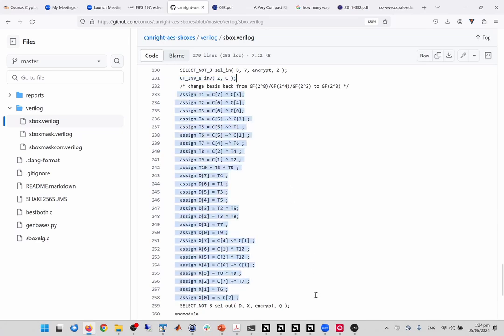And then based on which polynomials you select for the conversion in this tower field, they affect the number of XORs and the operations that you have. This way, you may have the smallest implementation or even a bit larger implementation. These are the things that should be considered when somebody makes the Sbox and the Sbox inverse.